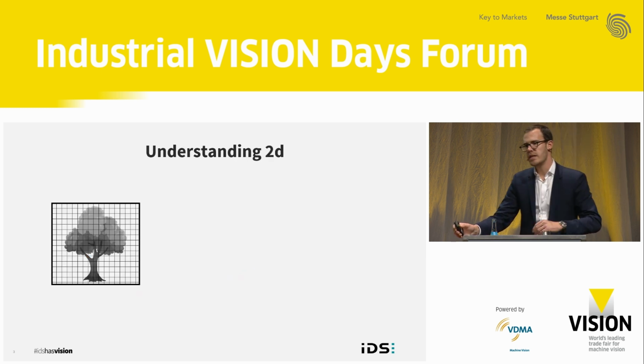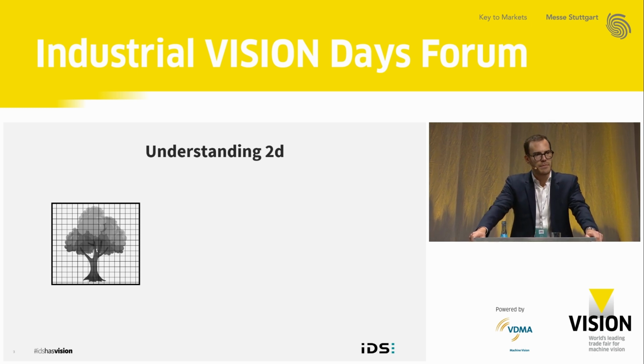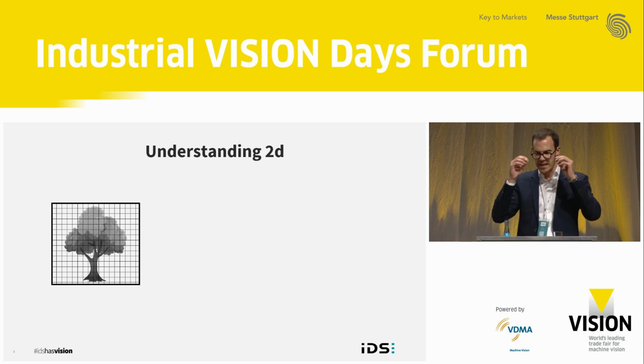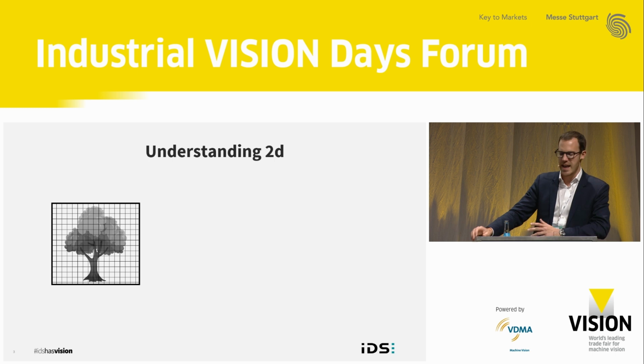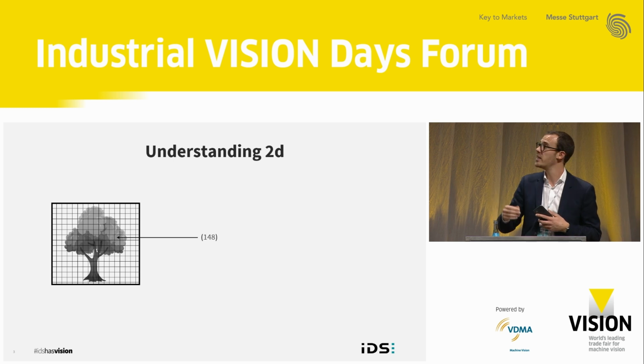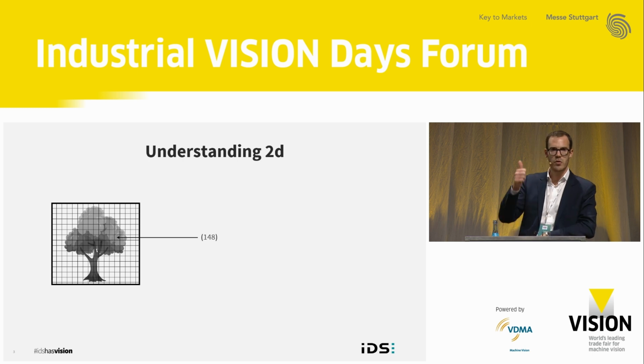When you take a look at a 2D image, in this case a monochrome 2D image, it's a matrix of pixels. With high-end sensors, you have a lot of pixels. With low-end sensors, you have not so many pixels. And each pixel is typically encoded in 8 bits. It can be more, but most of the time, when you talk about your phone, for example, it's 8 bits per pixel because this screen or this video projector is only capable of restituting 8 bits per pixel. So that's one piece of information for one pixel. The higher the value, the brighter the pixel. Okay?